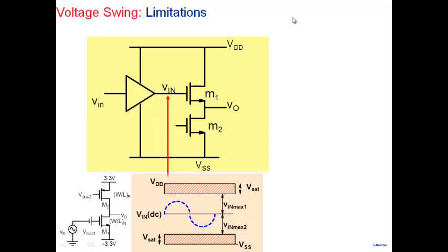this amplifier, as I said, is going to be driven by a previous amplifier, a gain stage. What is a good gain stage? Actually, you're not going to use a function generator or something like that to drive it. The driver for this is going to be a previous stage, and the previous stage I've shown you is something like this, a common source stage with an active load.